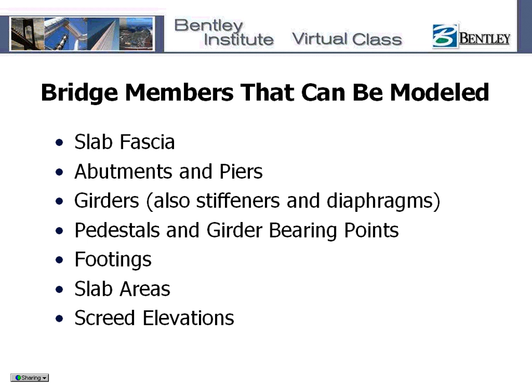You can also report on layout abutments and pier lines, along with the center line of the bearing lines where the girders bear on the piers and abutments. You lay out the center line and all the vertical and horizontal geometries of the girders, also stiffeners, diaphragms, splice points. All that can be stored in the geometry as well.